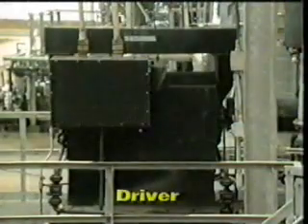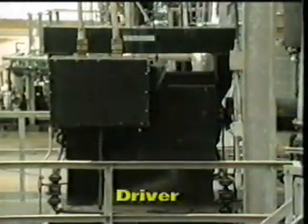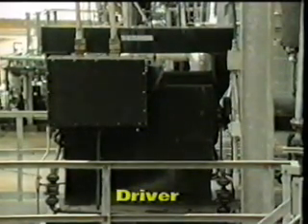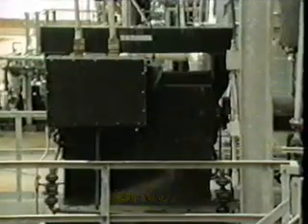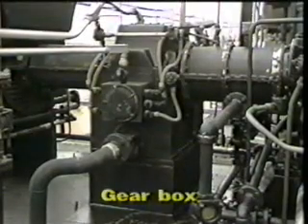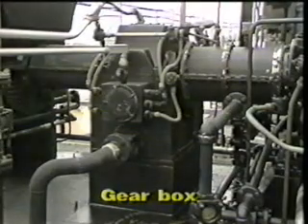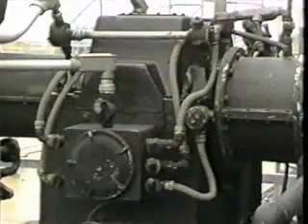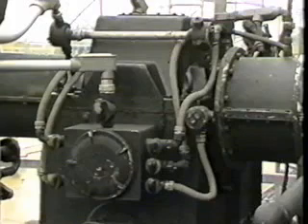The driver is the part of the compressor package that supplies the power to the compressor. It can be an electric motor, a steam turbine, or a gas turbine. A gearbox is often used between the driver and the compressor. This allows the compressor to run at a different speed than the driver. This gearbox may either be a part of the compressor casing, or it might be in its own separate housing.